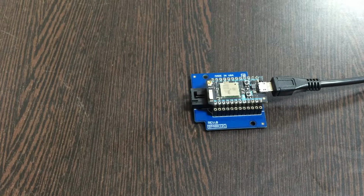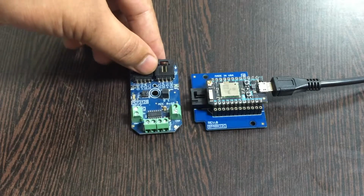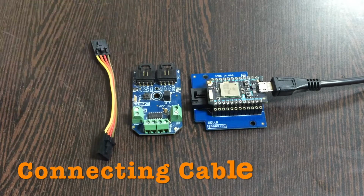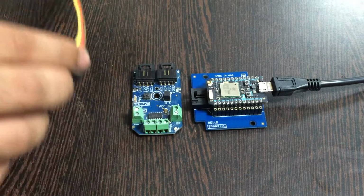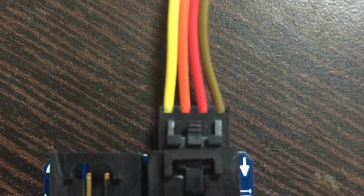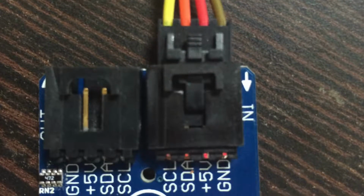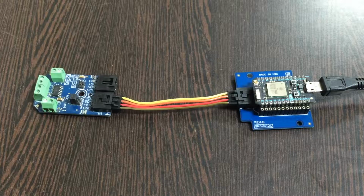Next, this here is our analog to digital converter, that is MCP3428, and this here is a connecting cable. Make sure that while making a connection with the cable and the ADC, the brown wire of the cable should be connected to the ground terminal of the ADC, and similarly to the ground terminal of the I2C shield. So these are the connections we require for this hardware. Now let's proceed with the code.